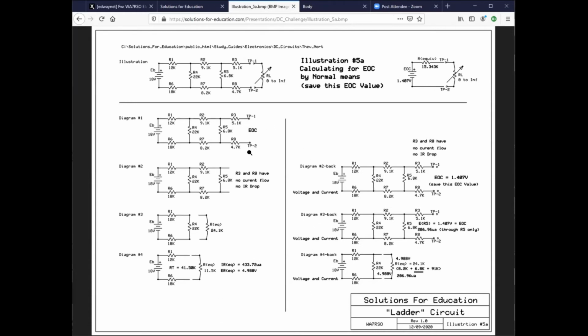What you're going to find is that what goes on out here at this point is only going to vary within certain points. Now here's where we're heading for all this. This circuit up in here is what we're heading for. See how we got 1 voltage, which is a whole lot different than this 18 volts? As it turns out, as you go through the circuit and figure it back up here, you'll find in this area here, the open circuit voltage. That's EOC. What it stands for is voltage of the open circuit variety. Okay, that's really what this is. 1.407 volts is the open circuit voltage. That's the voltage we use up here.